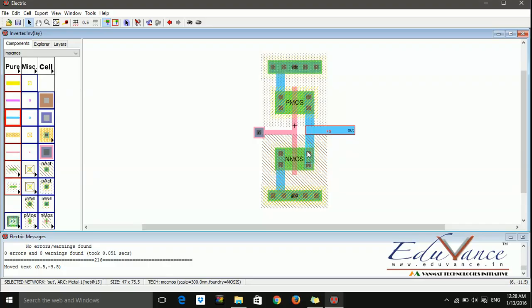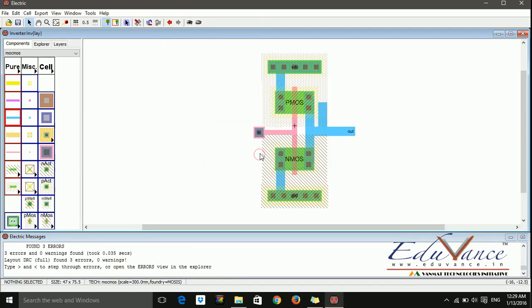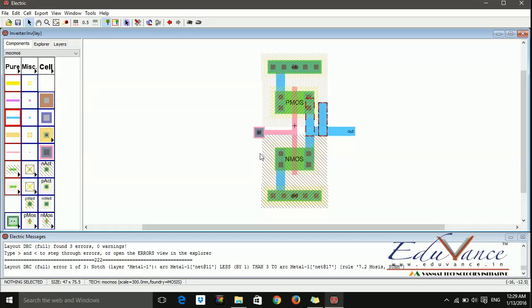This entire thing is one, with metal one over it. Correct? We've connected the drains through metal 1. So let metal 1 be anywhere, it doesn't really matter. But if I had something like this and it was close enough, then this would be an error. See? Too close, right?